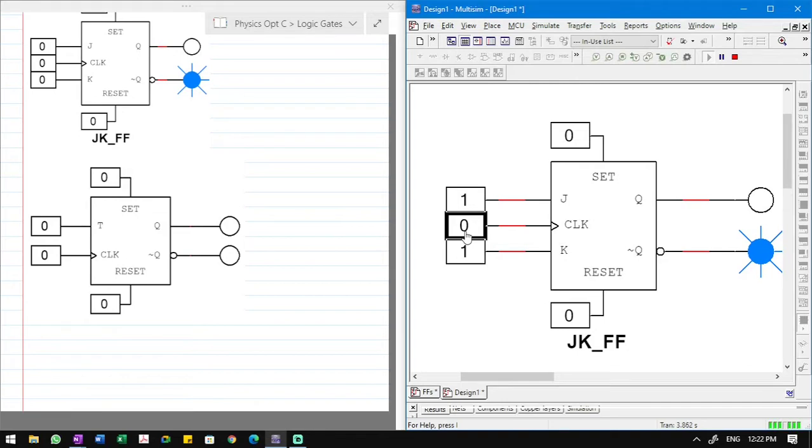Now, in the JK flip-flop, what actually has control of the circuit on the input side, and remember, I'm ignoring the set and reset above there, right? Typically, we don't put them in, right? Anyway, the outputs of the circuit are actually controlled by the clock in the JK flip-flop, right? So J and K don't really control the output, the clock does, right?